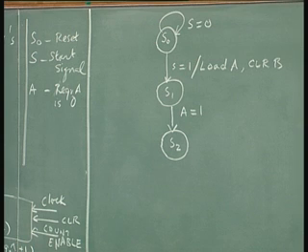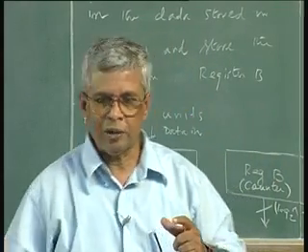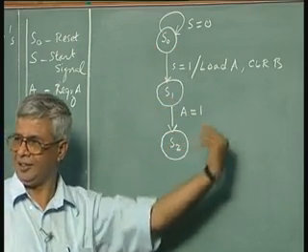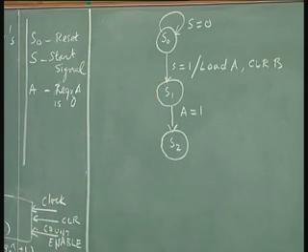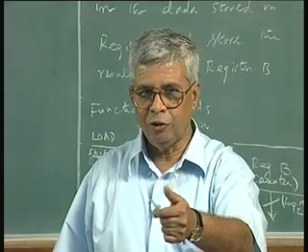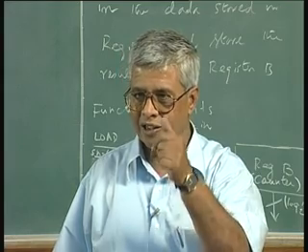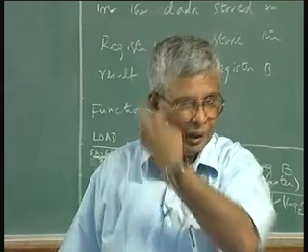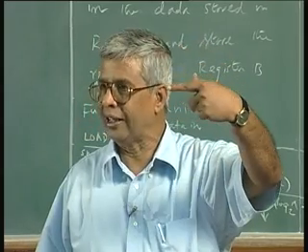S is a signal which is start signal. It could be a manual signal. Somebody pushed a button. If I do not make sure that S is 0 again, I may go back and redo the same thing. Supposing I have a non-zero value of A and it is going to take just a few clock cycles to count the number of ones. Still, if you do not release the start signal, you make a start signal 1 and you have started the work and you completed the work and S is still 1, I will go back and again it will redo the same thing over again. I do not want to do that.